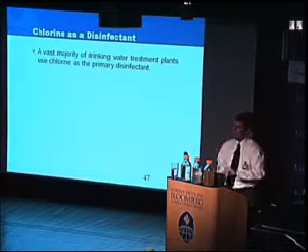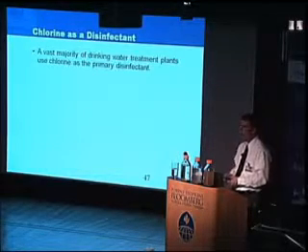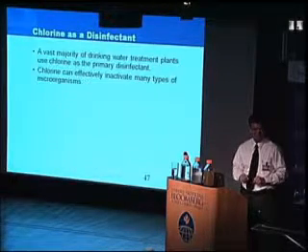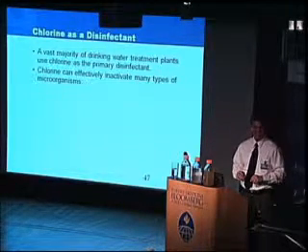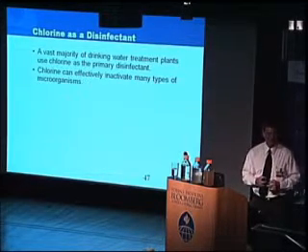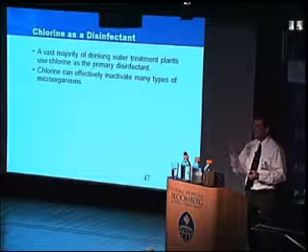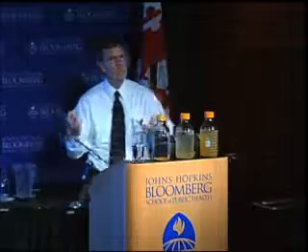What we use in most systems now is chlorine. Chlorine is promoted around the world. It is in most drinking water systems here in the U.S. and around the world. It effectively inactivates most microorganisms. Anybody from Milwaukee? Milwaukee had the largest outbreak in the United States in '93, and what they had was cryptosporidium. It's a protozoa that does not react with chlorine. So they had an outbreak in the city, and half the city got sick. Why half the city? There are 2 treatment plants. One treatment plant didn't work well, the other one did. So that's the challenge. But the idea is chlorine has been very effective, and it can inactivate many types of microorganisms.